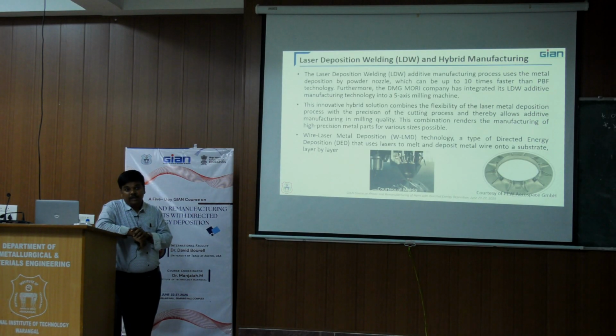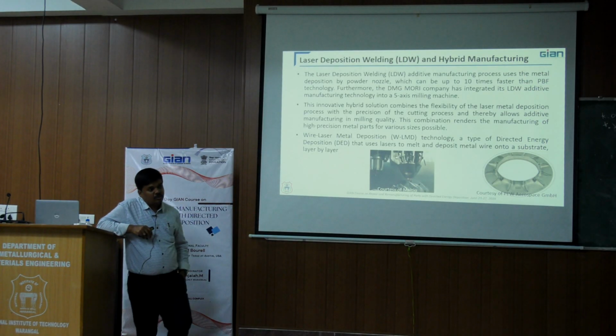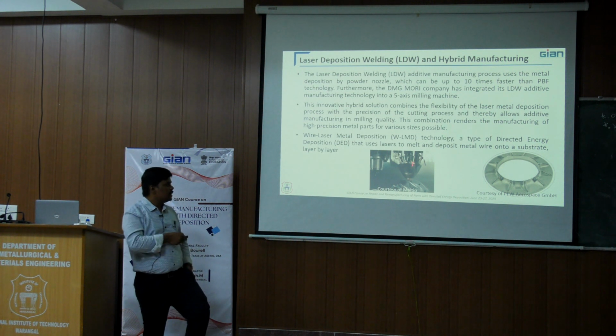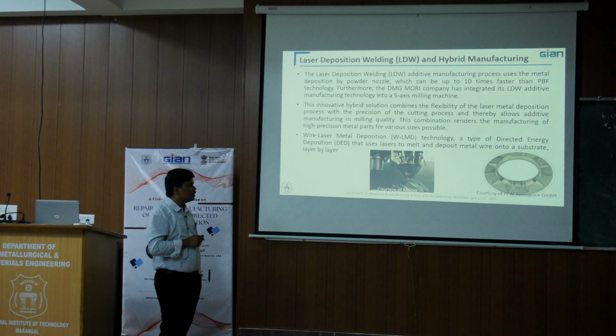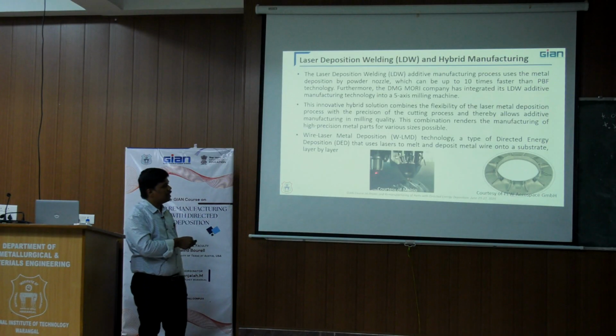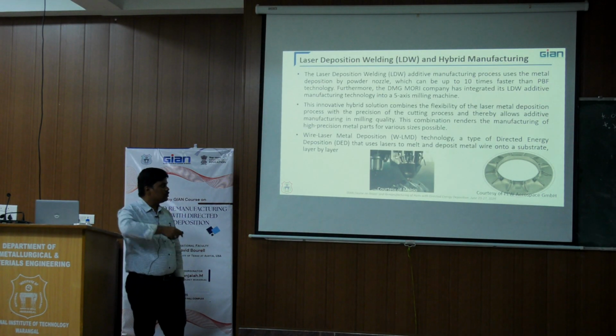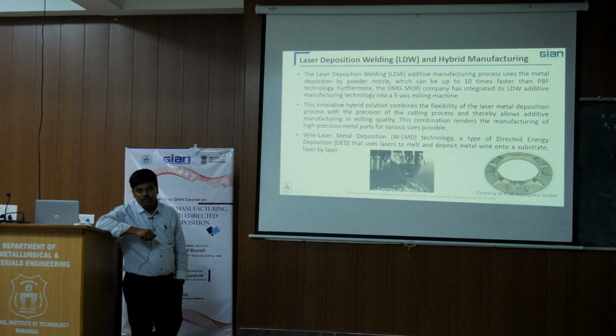Another thing I wanted to mention is the laser wire DED process. Beltio, as well as PFW Aerospace in Germany, have made a lot of developments with respect to wire-based systems. Earlier it used only an arc or an electron beam to melt the wire. Now they have made laser wire. This is the hybrid technology I was talking about. They have a milling head as well as a deposition head.